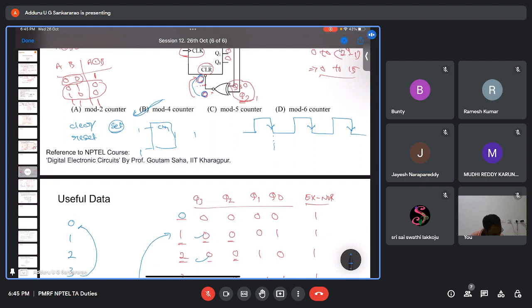That means somewhere here you applied the clear input. The negative edge trigger is not there, but still this will change the state of the flip-flop. Somewhere here you applied it, and till here the output of the flip-flop is, let us say, 1. Now suddenly here you applied the asynchronous input, then the flip-flop output will change from 1 to 0. You need not wait till the clock comes. That is actually how the asynchronous inputs, set and reset inputs, work.